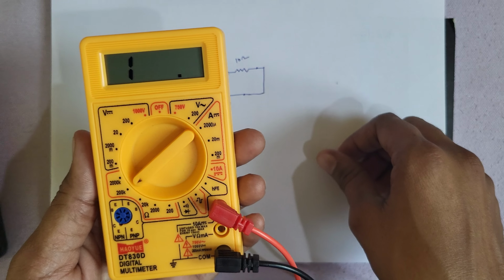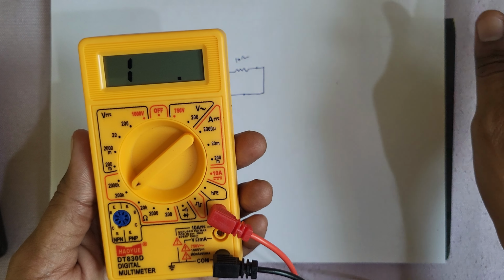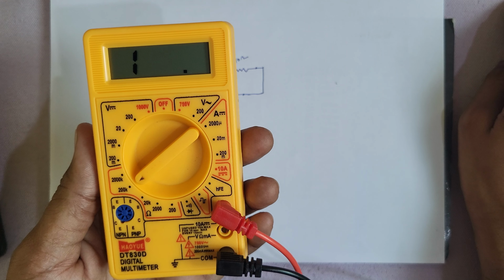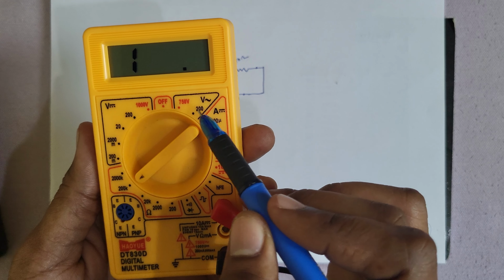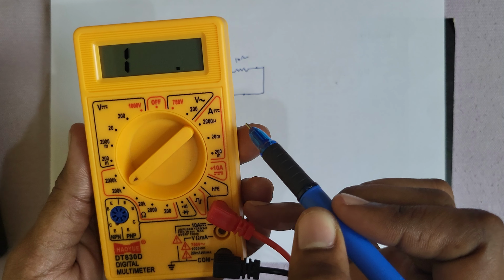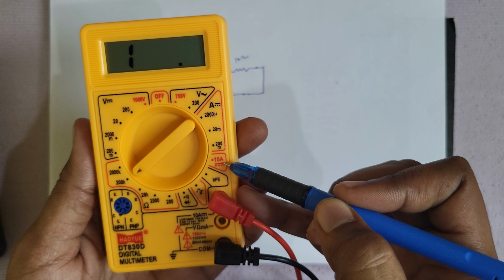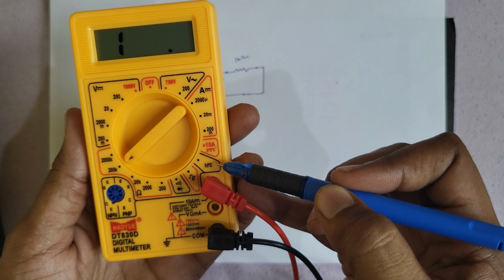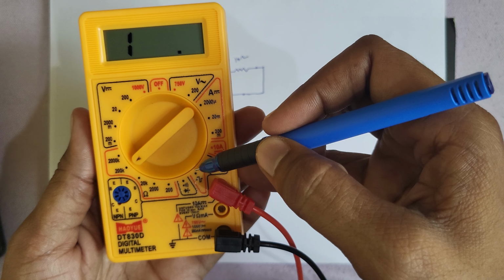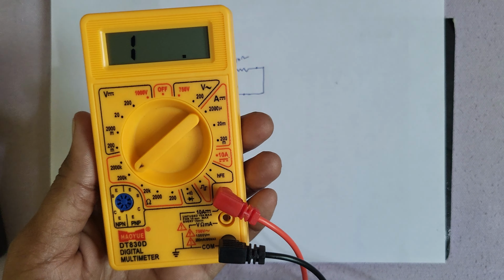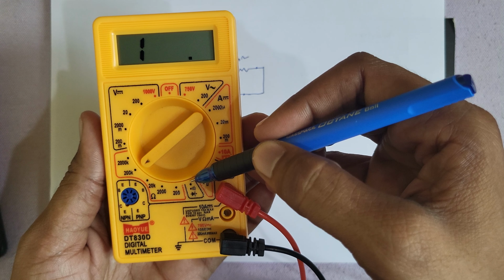We know it is a multimeter and we can measure anything using this multimeter. What can we measure? Voltage of DC voltage, voltage of AC voltage, current of DC current, afterwards a maximum current of 10 amperes, and afterwards hFE, which means transistor gain. And this is also used to verify some transistor operations. And now this is used for continuity and for diode.